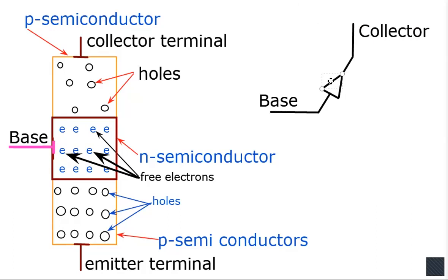We should change the direction of the arrowhead. In the circuit symbol of a diode, the arrowhead gives the direction of the current when the diode is forward biased. Forward bias current flows from P to N. Therefore, the arrowhead should point into here.